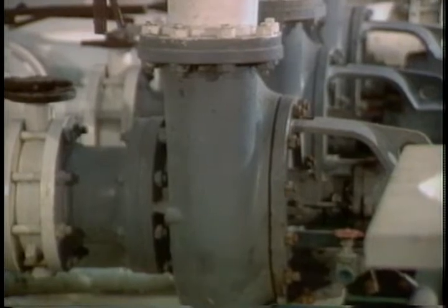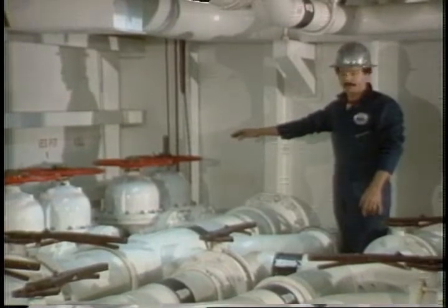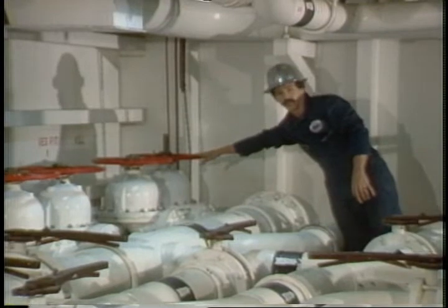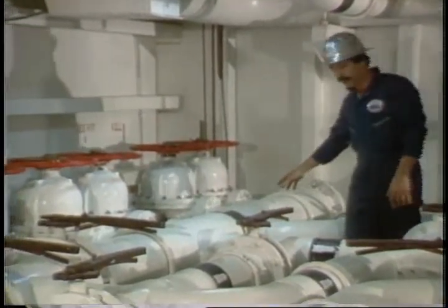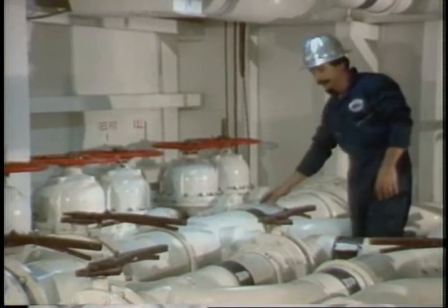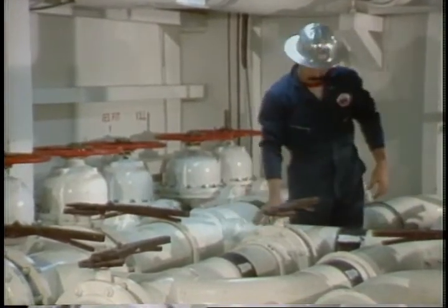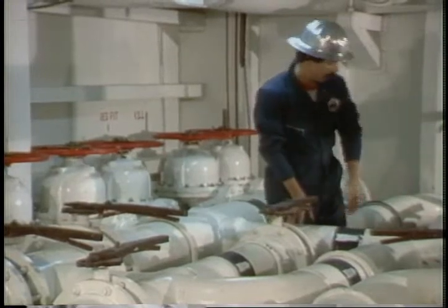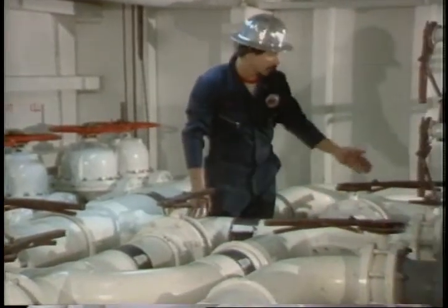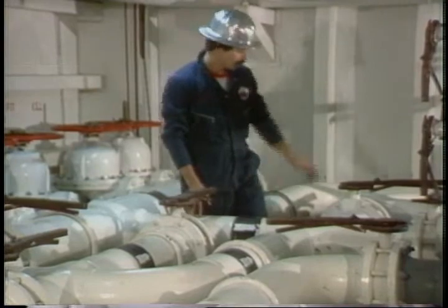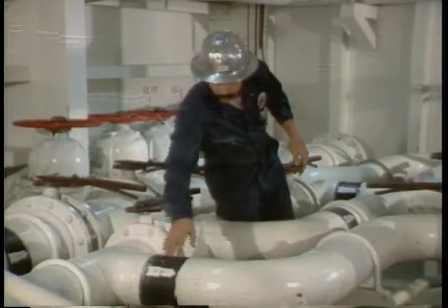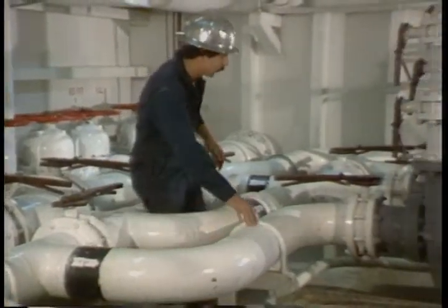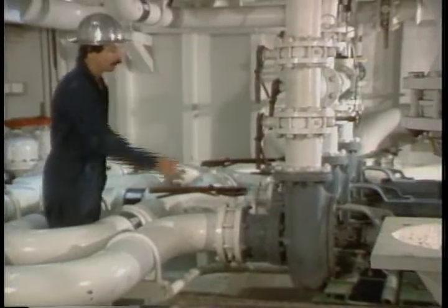I'm going to be drawing mud from my kill pit through this suction valve, through this 12-inch line. The route it's going to be taking is coming through the line. It'll be coming through this smaller line. The mud will go right here and dead end because the valve is shut. It'll come back and it'll go through this route here. Continuing on, it'll go all the way through this line, around this L, back into the centrifugal pump.